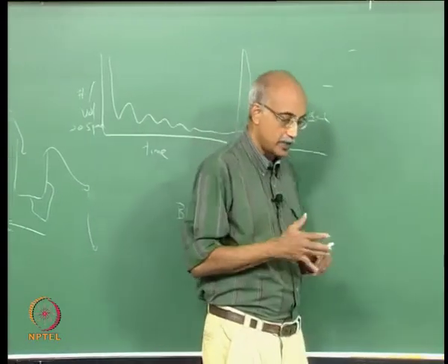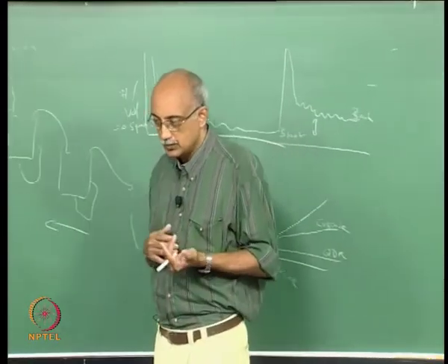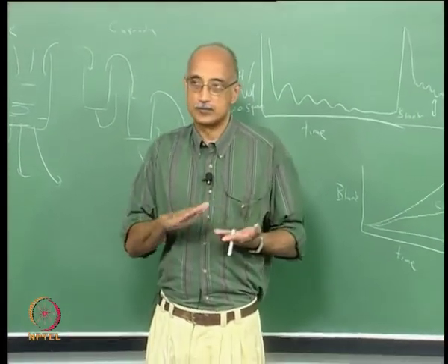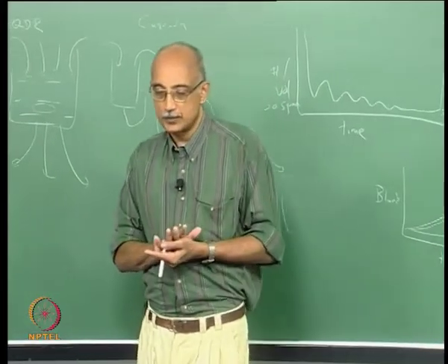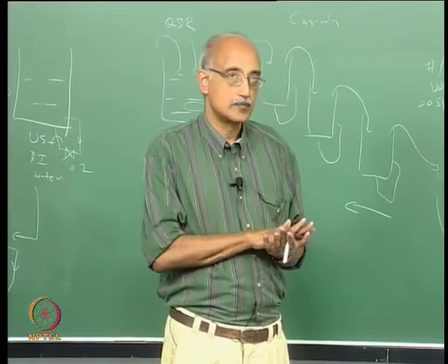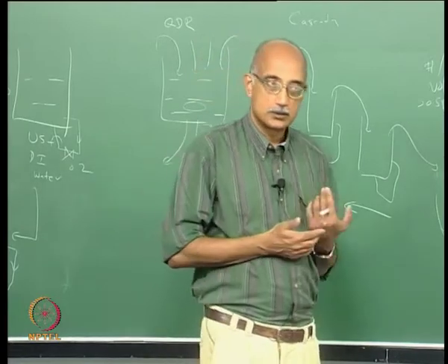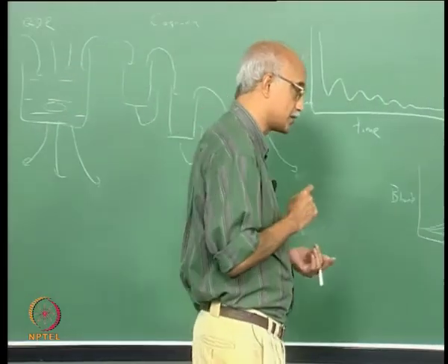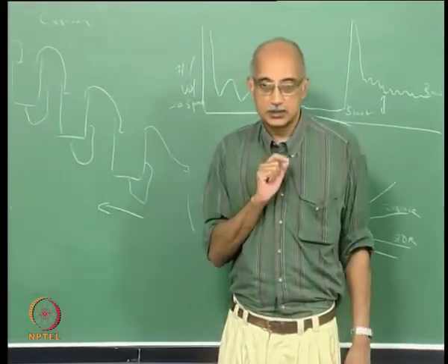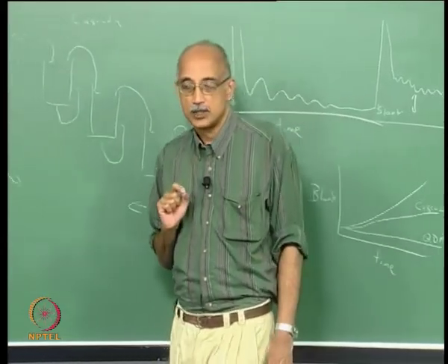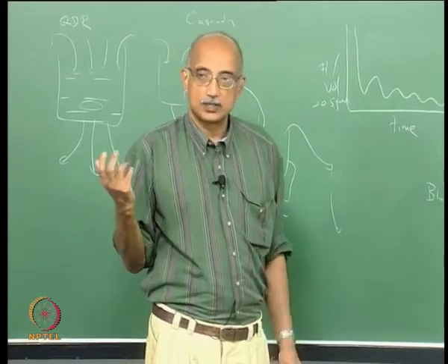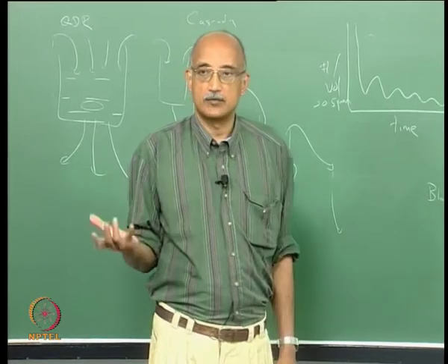So, continuing in the high tech manufacturing side, another application that is widely used, particularly again in silicon manufacturing, is deposition of thin films. Thin film deposition is an essential step in order to incorporate the right type of semiconducting and non-conducting and conducting elements on a surface. Thin film deposition is again a process that is very much dependent on particle characteristics. However, in this case, the effect of particles is somewhat indirect. Now, thin film deposition is essentially done using two different processes. One is physical vapor deposition and the other is chemical vapor deposition.